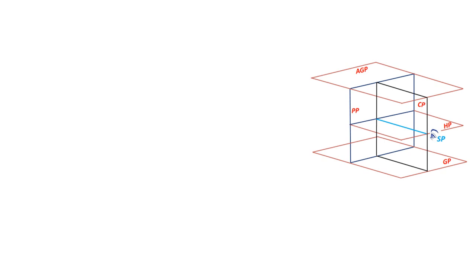Okay, the entire element shown here is actually a 3D system. As we all know, the perspective projection is a pictorial representation of a 3D object onto a 2D plane. We need to convert this system into a 2D system. For that, we need to draw the front view and top view of all the elements by using orthographic projection.